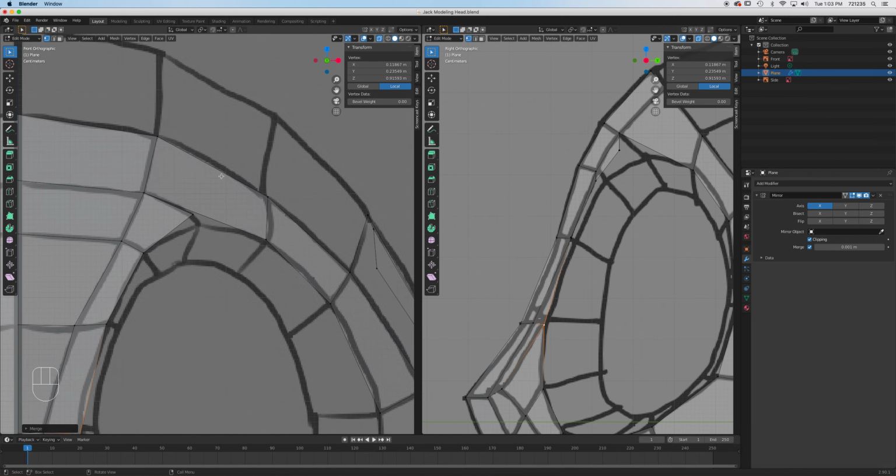And now this issue right here where I made this missing line. So I'm just going to do Control R right here. And, well, actually, let's not do that. I'm just going to snap this. I'm going to ignore this drawing right here. I'm just going to snap it to that. Okay. Merge last. Oop. Only that one. I selected too many. M at last. All right, so there's that.